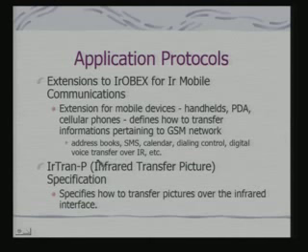Okay? So, you are actually having a GSM device, it has got its GSM capability, but you are providing the interface for those GSM functionalities through the IR link. And so, you define protocols specifically for these kinds of applications. Then you say infrared transfer picture, this is another protocol, how to transfer pictures over the infrared interface.